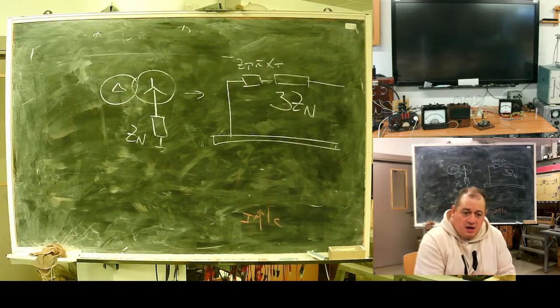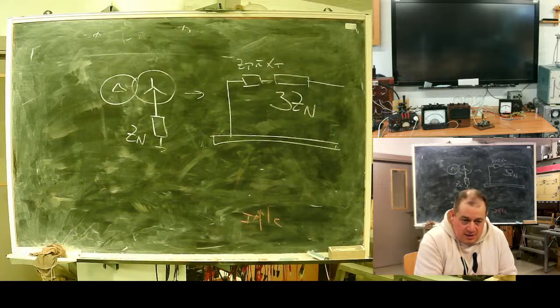In the book, Carson's model is described, and usually the data in the line reference are from Carson's model. It's a low frequency model. In case you need high frequency, get a good book or good software or hire someone, because you will need something much more complicated.